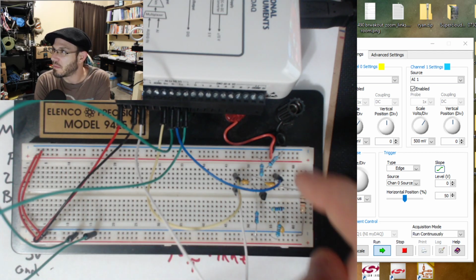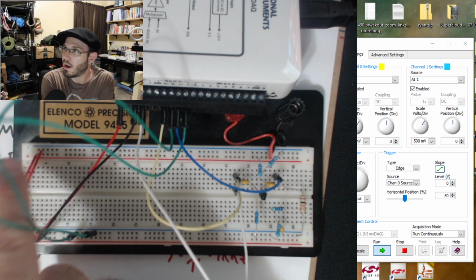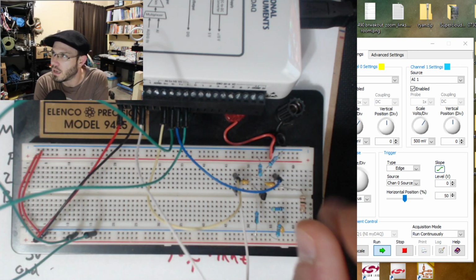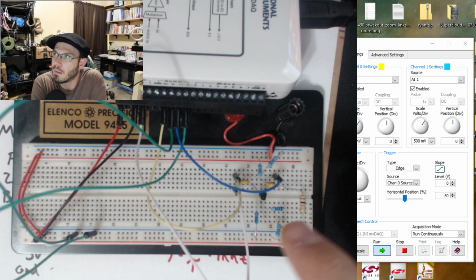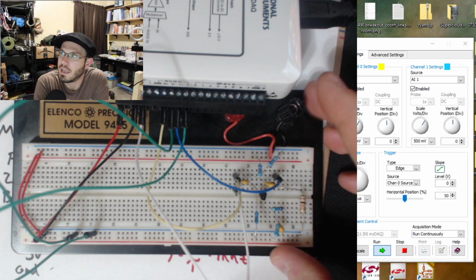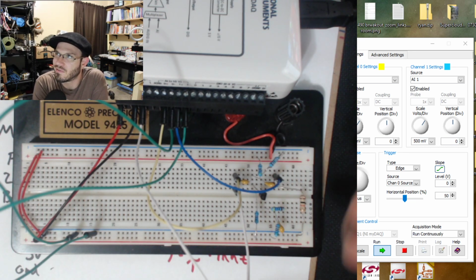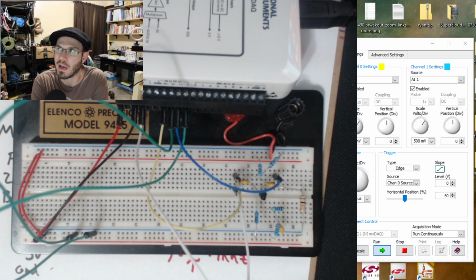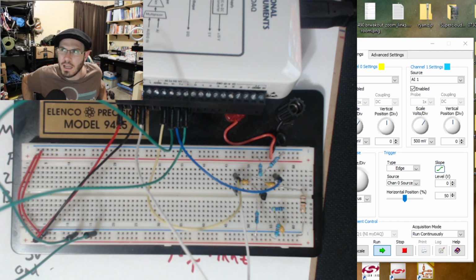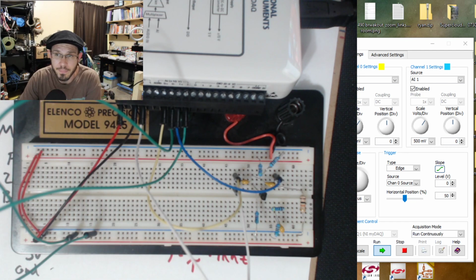And in this case, I'm using it up here. And so it's going through my wire all the way to the top and over here. And if you've noticed, I've constructed my common emitter amplifier circuit fairly cleanly, and I've done it without using an excess of wires just to keep it clean. I try to use the component leads as much as possible, to cut down on problem areas and bad wires and things to that degree.